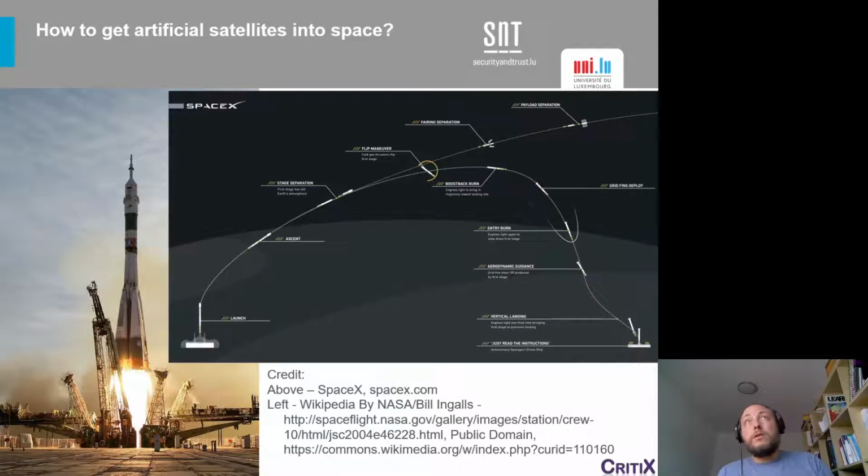first cosmic velocity, and it's about 7.9 kilometers per second for Earth because it depends on the size of the planet. And in fact, this has to happen obviously above the atmosphere, so at least 100 kilometers above Earth's surface. But actually, then you have still a residual drag. So the practical orbit starts to be at 350 kilometers above Earth's surface and higher.